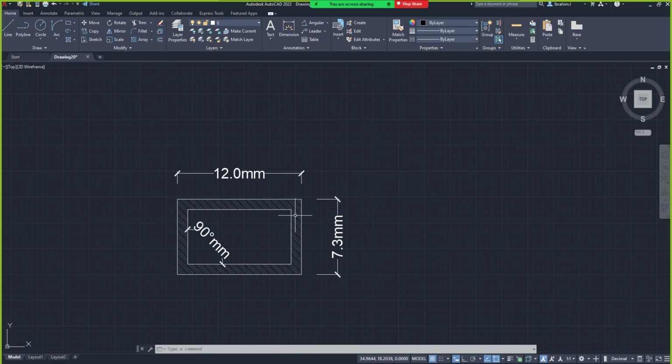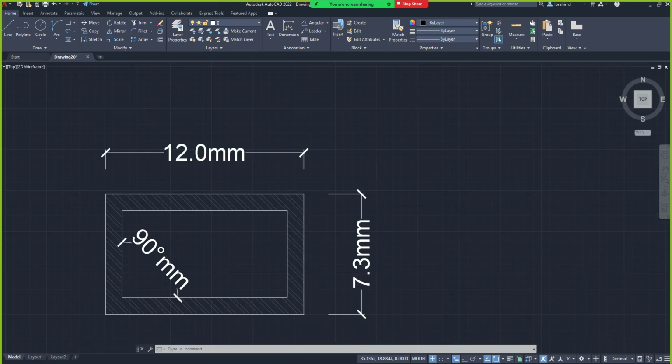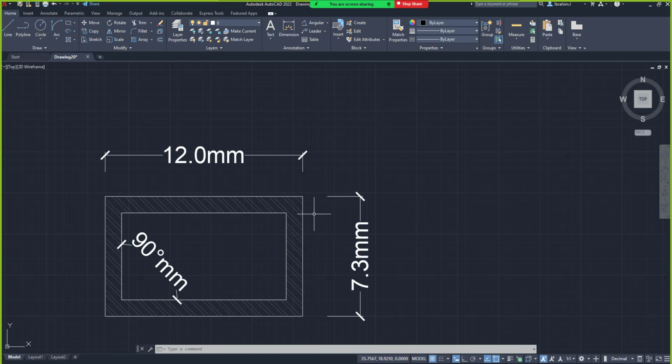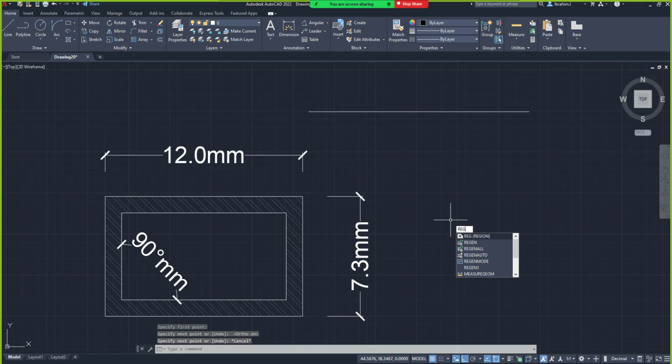Sometimes you can even have graphics error if we are using a system that is not actually very compatible. So sometimes your straight line, using your line command like this, can appear as if it's broken. How do you correct that? You can use regen for that. When you regenerate, it will help you adjust your design to view. So in AutoCAD, regen is very important.